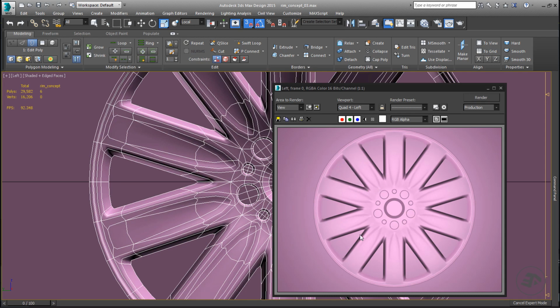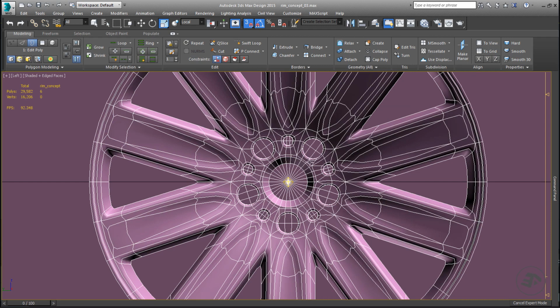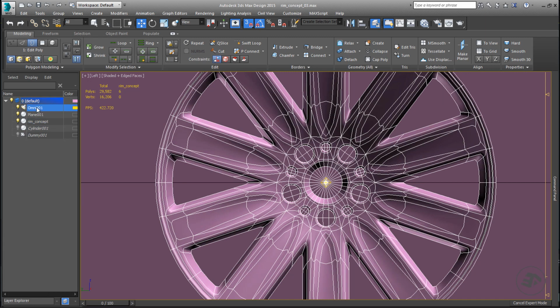One of the most important settings of the light is the light coverage. Bad light coverage can cause dark lines or dark areas over the geometry. The Omni light creates a circle or a conical shape from its center, hypothetically speaking. Obviously, this imaginary light shape is not wide enough to cover the peripheral parts of the rim. Unfortunately, we do not have any indicator for how wide this circle is inside the viewport.